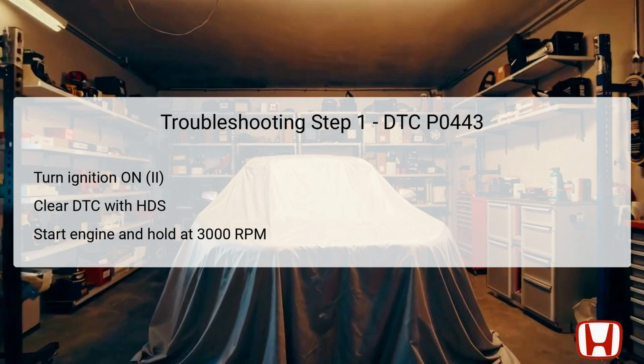First, turn the ignition switch to the on position, labeled as II in Honda vehicles. This action powers up the vehicle's diagnostic systems, allowing you to observe any stored data. Next, utilize the Honda Diagnostics System, HDS, to clear the DTC and reset the onboard computer's readings.